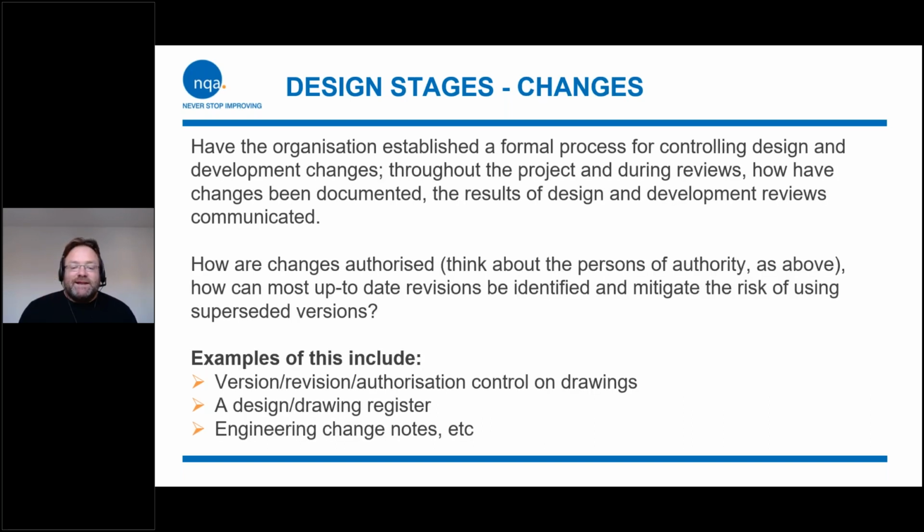Changes, same as anything in life, can happen, and when changes happen within design, the standard asks that you control those changes, be it drawings, prototypes, that kind of thing. Any changes that happen are absolutely fine, but you need to make sure they happen in a controlled manner, that there's authorization, and that they've gone through any necessary verification and validation. Don't let them be uncontrolled. Make sure the changes are authorized and as they need to be.